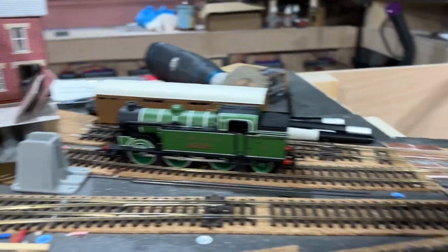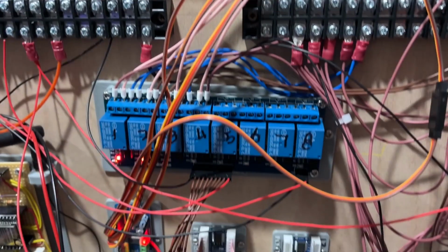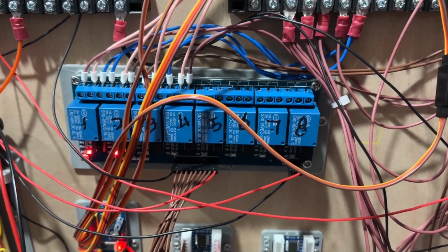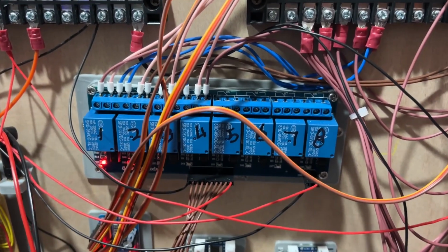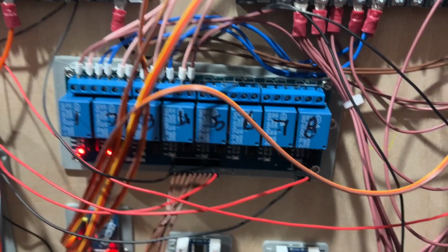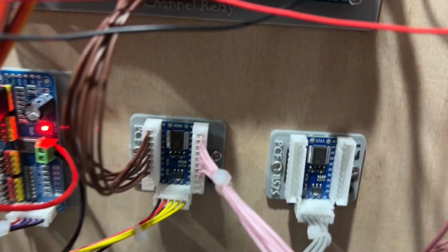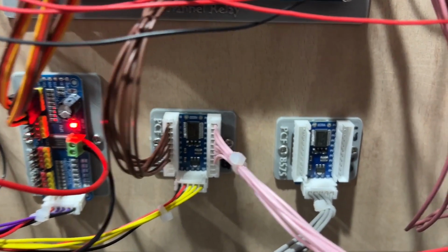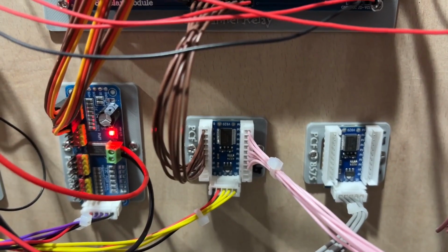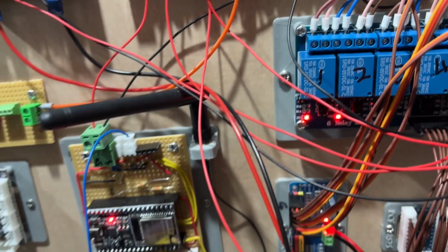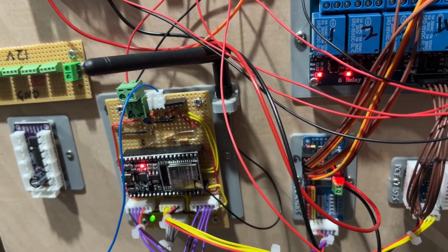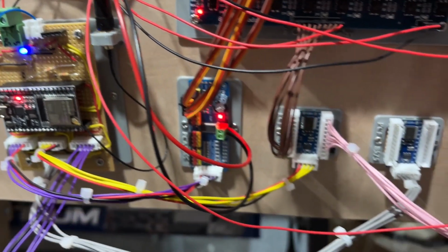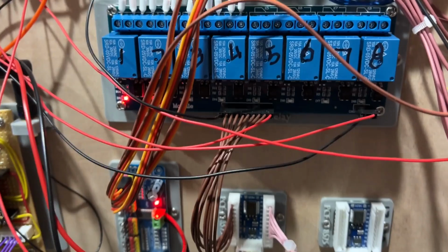It's very, very simple. The frogs are controlled by these relays. Boards that have got points have got them. This one's got 8. It's only, I think, going to use 6. Each frog gets its own point. It is connected again to the little PCF 8575, this time using some outputs. So I've got the pink wires are inputs, the brown wires are outputs. When the ESP32 says I'm going to throw the point, it sends the servo instructions to the servo. It also sends an instruction here which changes a relay.